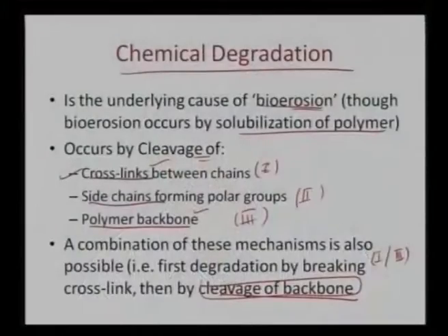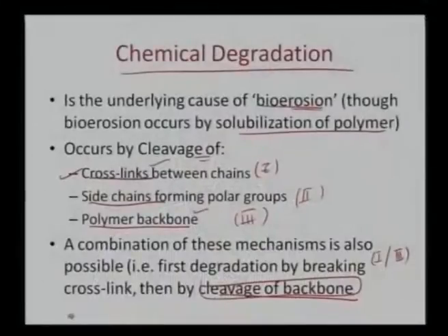So there might be certain causes of bioerosion, but the fundamental cause of bioerosion is basically chemical degradation, and that degradation can be either the removal of the cross links, or the cleavage of the side chains, or the cleavage of the backbone structure of the polymer itself. Those are the basic reasons for chemical degradation.